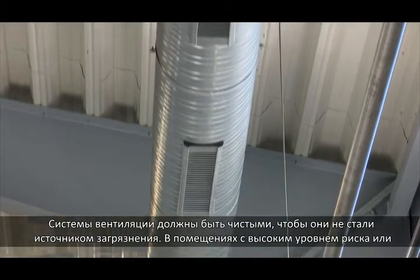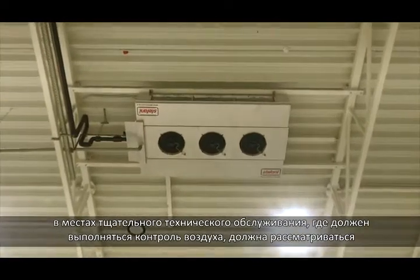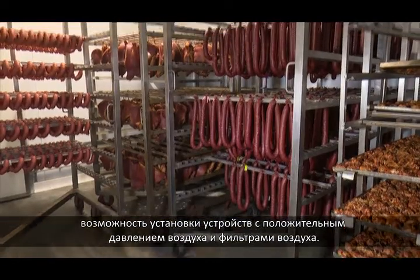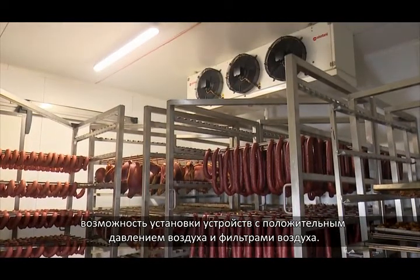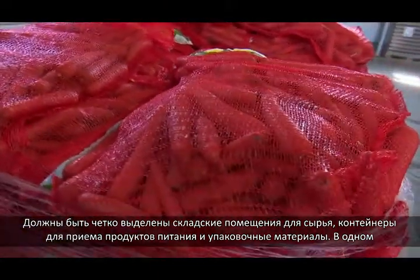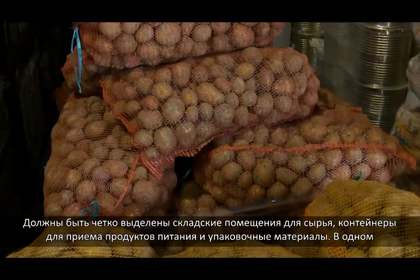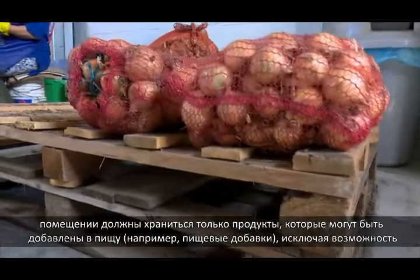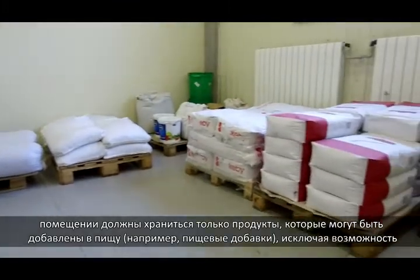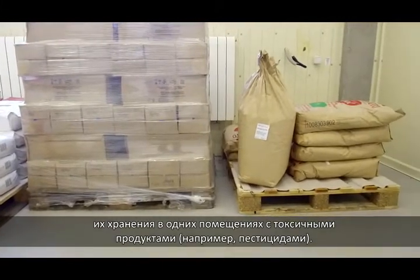Ventilation systems must be clean to prevent them from becoming a source of contamination. A possibility of installing positive air pressure and air filtering devices must be considered at high risk or thorough maintenance premises where air control must be performed. Clearly separated warehousing premises must be provided for the raw materials, containers for the receipt of food, and packaging materials. Only the products that can be added to food, for instance food additives, must be stored in one area, excluding the possibility of storing them in the same premises with toxic products, for instance pesticides.